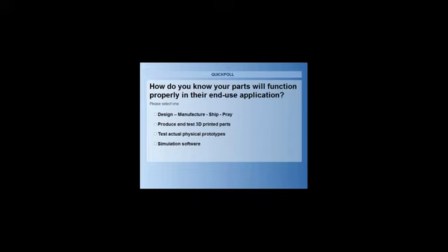Can CFD calculate ducted fan performance? Yes, it can, absolutely. What version of SolidWorks is being used? Oh, Ron answered. So there's a question here about modeling composites in our FEA solver. You can do that. It's with a product called SolidWorks Simulation Premium. Basically you model it as a shell, and then you put in your layer stack up. So you put in each layer the material property and the fiber orientation.